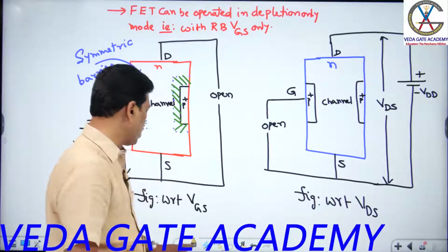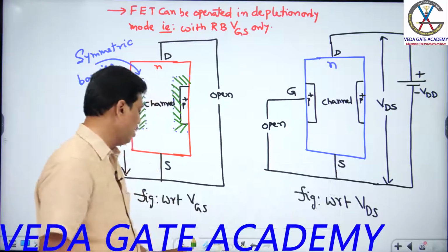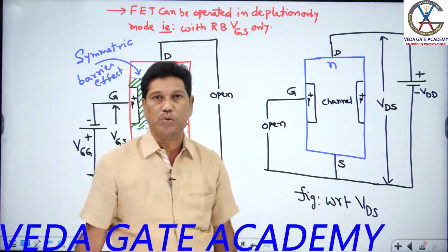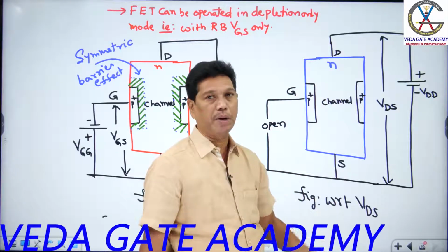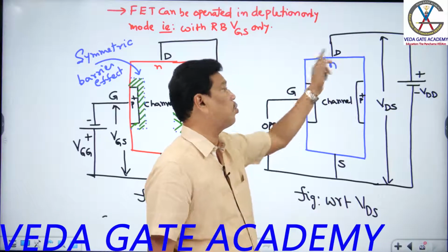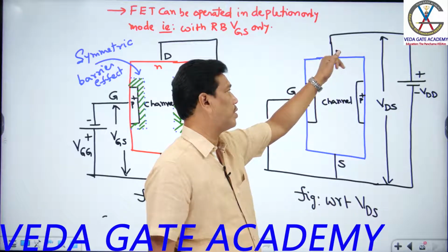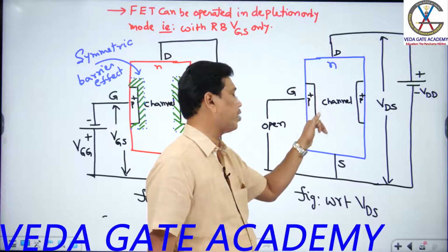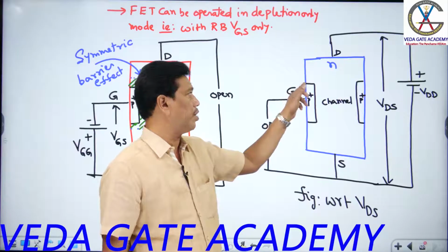So with respect to the drain voltage, observe now, students, on the channel. Towards the drain there is a reverse bias effect. So the drain is at reverse bias potential with respect to source. Because of this, the barrier is expanded by this drain voltage towards the drain only, not towards the source. So the barrier expands towards the drain, students, and while you come towards the channel of the source body, the barrier effect gets tapered. Tapered means reduced. So there is a reduced effect as you move towards the source, and this barrier expands